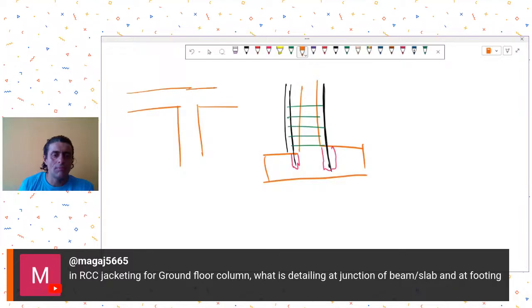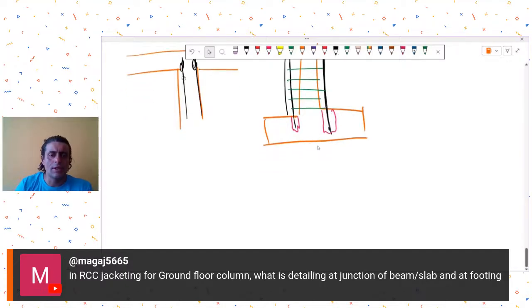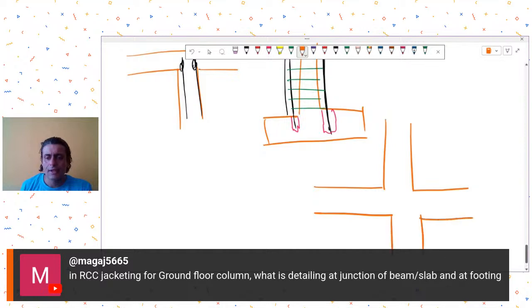Where you have a footing, a beam and column, things may become complicated. So let's say this column is terminating over here. You can again just drill the reinforcement inside, and that's it. But if your column is going to continue, it will be slightly tricky. Let's say I'm showing you the elevational view, and you have jacketed the column. So the column is now of a larger size.